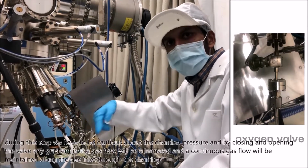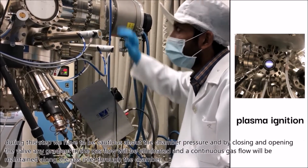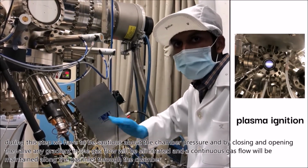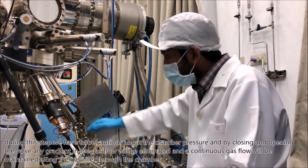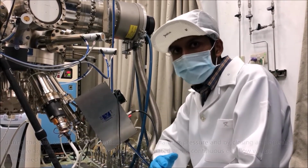During this step, we have to be very cautious about the chamber pressure. By closing and opening the valve, any gradient in the gas flow will be eliminated and a continuous gas flow will be maintained along the gas inlet throughout the chamber.